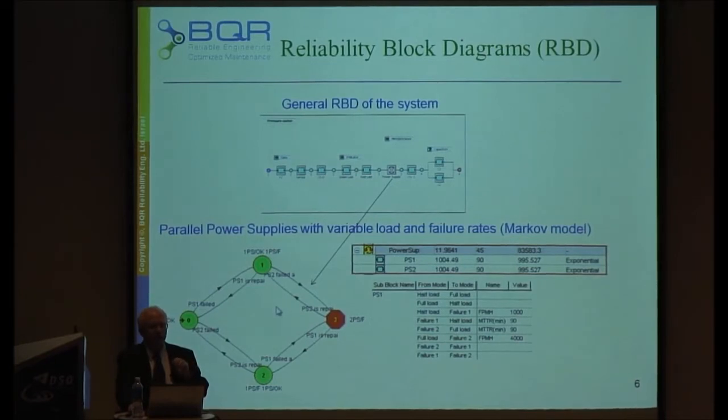So Markov is used when a component moves to another state. Let's say we convert it to a mechanical component like a bearing, which has, let's say, 16 balls inside. If one ball is not okay, it's still okay. The second is still okay. But the failure rate starts to increase because it's about to make noise, maybe it's a little bit loose. So we can develop a Markov model for a bearing saying the first ball failed, the second ball failed, and so on.